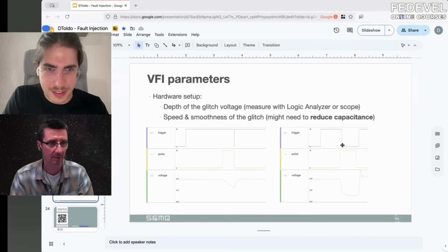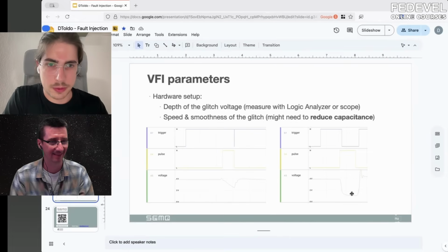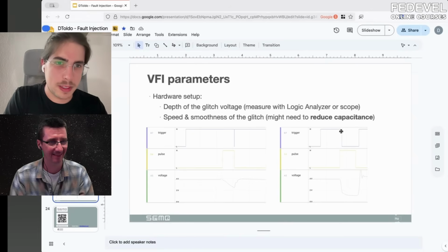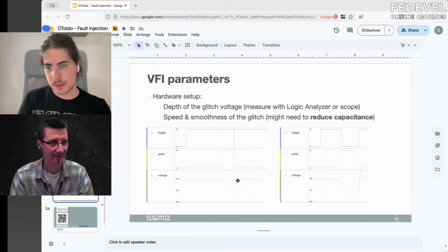What we see here is funny because this is a bug in the logic analyzer in a sense. Basically, I think that the voltage switching couples into the digital signal of the trigger, and in the analog world it probably only has a small dip here, but it gets picked up as a low signal. And here it's just a line. So even with this tiny glitch, it creates interference in the logic analyzer. So it's stronger than you think.